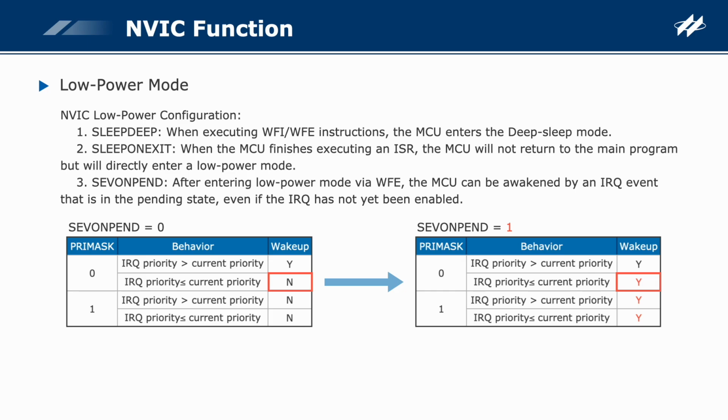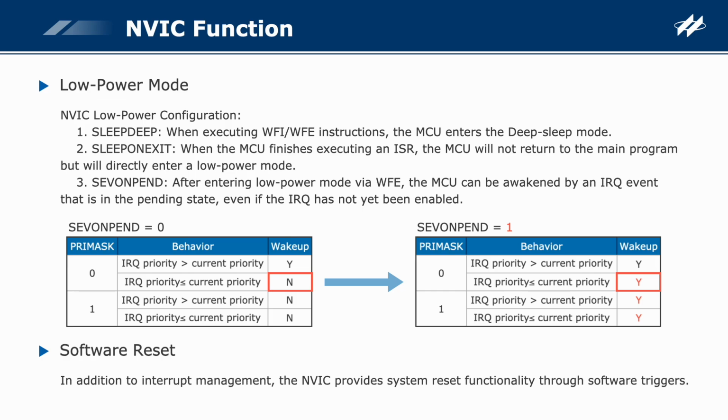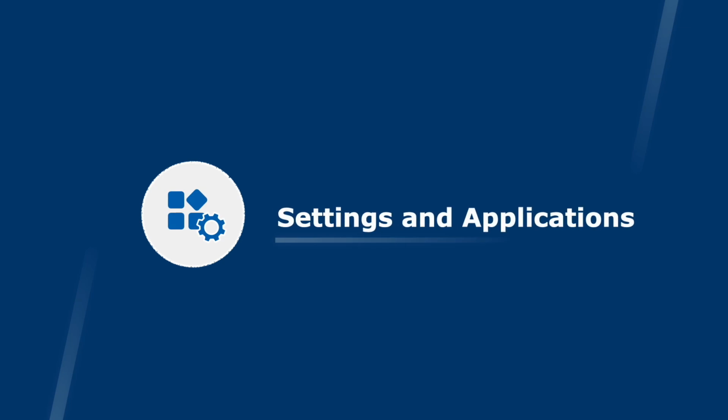In addition to interrupt management, the NVIC provides system reset functionality through software triggers. This allows the program to trigger a system restart via software, eliminating dependence on the external NRST reset pin hardware signal. Settings and applications.